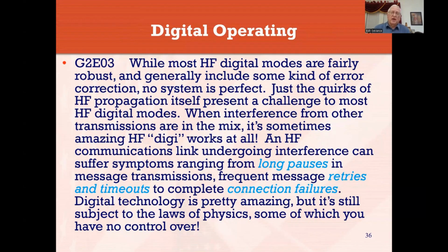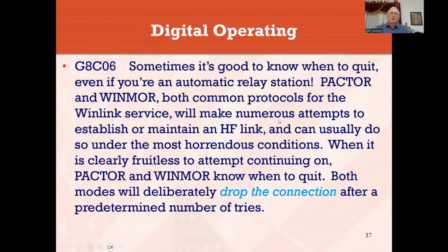And the answers are, you can have long pauses in the transmission, frequent message retries and timeouts, and a connection failure. So the two radios are going back and forth trying to communicate with each other. And if it gets to the point where they can't, then the receiving end of it will basically just say, I quit, and stop listening to you, and just break the connection from you. Sometimes it's good to know when to quit.